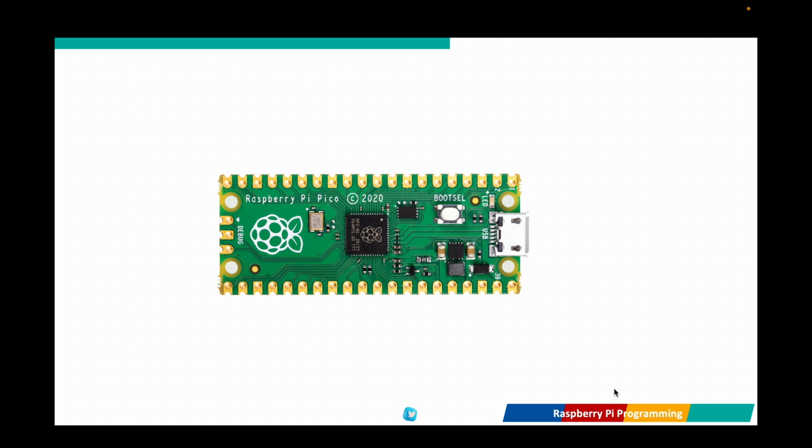The Raspberry Pi Pico is a compact and energy-efficient microcontroller board designed for embedded systems, automation, and IoT applications. The Pico is built around a microcontroller and is optimized for low-power applications. Let's break down its key components. The main microcontroller is the RP2040, which is the Raspberry Pi microcontroller. It is a custom-built dual-core ARM Cortex-M0+ processor running at 133 MHz.